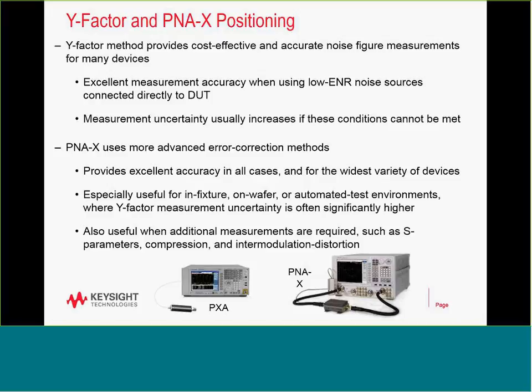Comparing the Y-factor technique and the PNA-X technique for cold source noise figure, they both still have their place. One does not replace the other. The Y-factor technique is excellent for making low noise figure measurements. We're directly connected to the DUT, with a simple process, calibration, and in most cases very accurate measurements when your device has a very good impedance match.